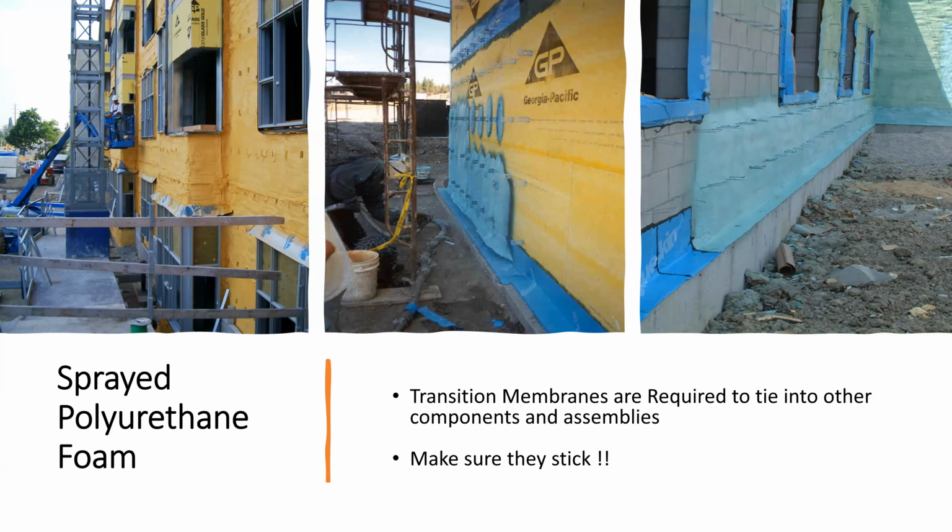And the reason why it's important with the spray foam is that these things are sprayed on fairly hot. It's two chemicals coming together under pressure and temperature. When you spray it on, it gets very, very warm to the touch. Once it cools, it starts to contract, and as it contracts it has a pretty big force that wants to rip things off. So when you are spraying over a membrane, the installer shouldn't be blasting it on thick. They should do thinner passes with not as much heat buildup.